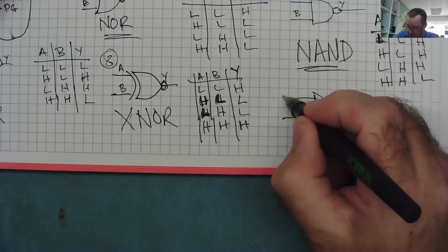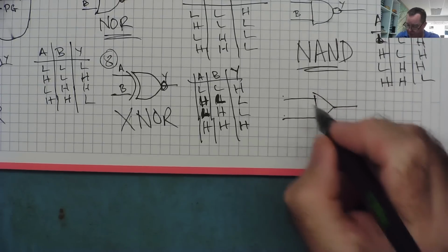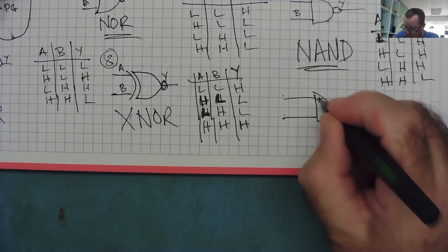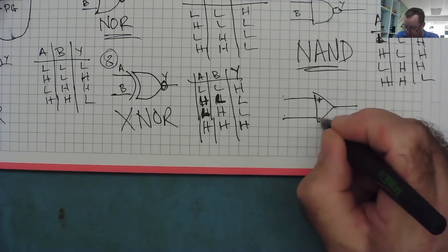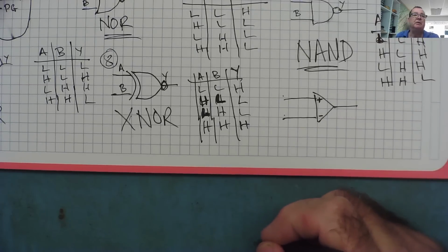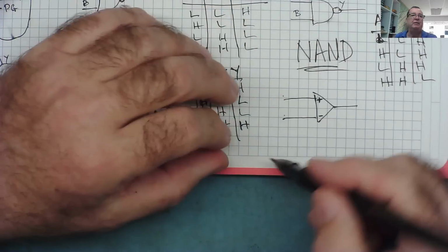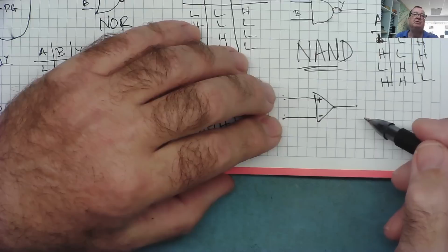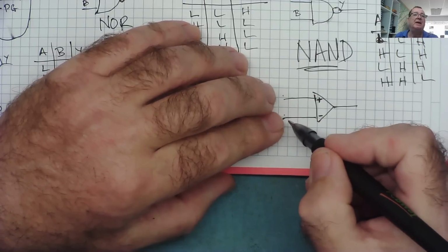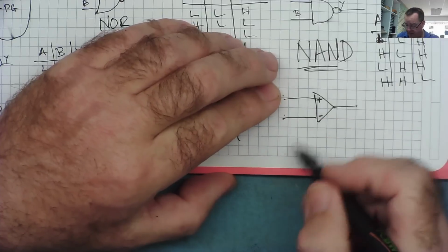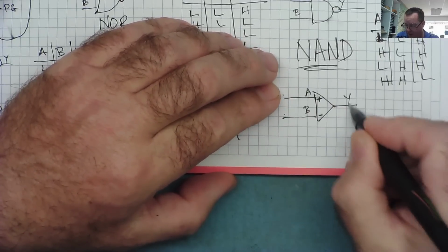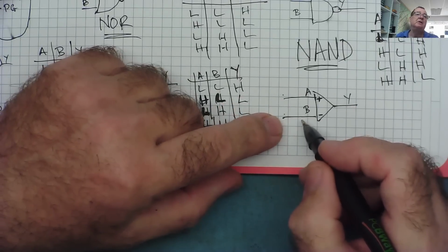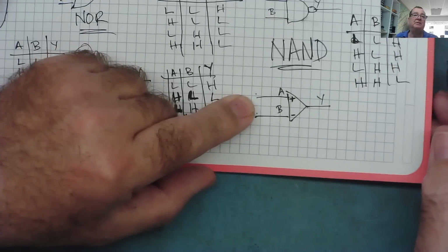And what it does is it compares the voltage on this input with this input. So this is analog. The voltages can be anything. This is the plus input. Sorry, this is the non-inverting input. This is the inverting input. Okay, and it effectively, although these are analog, compares the two and gives basically a digital output. So if the voltage on here, we'll call them A and B again, let's call this Y again. If A is higher than B, it will give a 1, and if B is higher than A, it will give a 0, high and low.